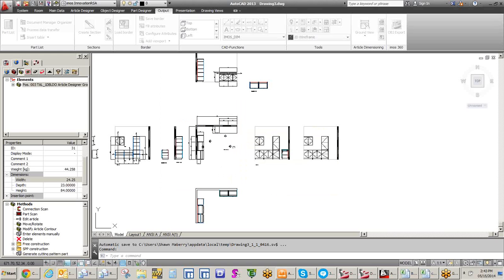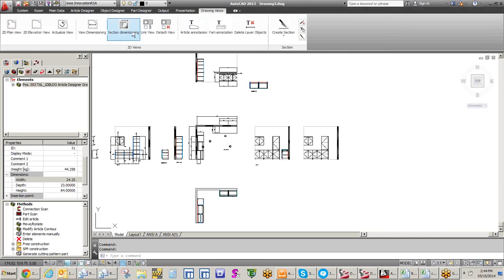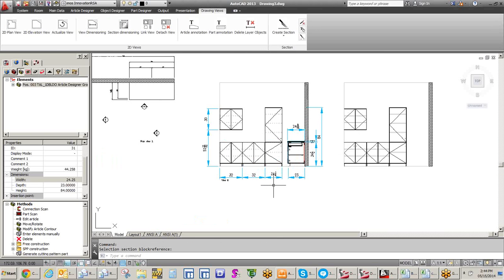Now the dim style that's going to be used is layout dim, and go ahead and dimension the ones that don't have any dimensions. Not that, that's view dimensioning. Okay, completely different dim styles, and these dim styles are saved in your DWT. So Larry, does that answer your question that you had earlier?